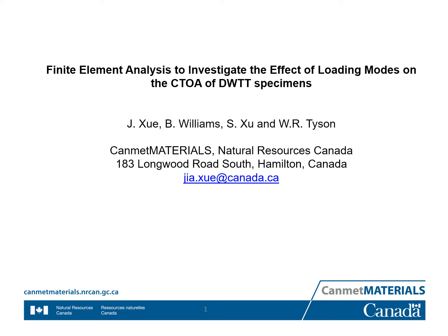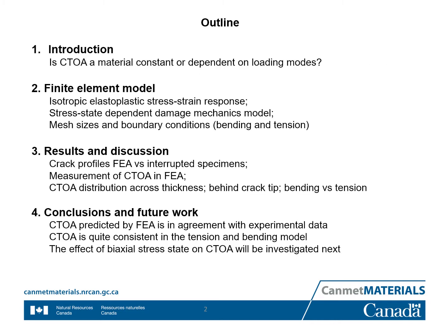The topic of my presentation today is finite element analysis to investigate the effect of loading modes on the CTOA of DWTT specimens. The outline of this presentation will have 4 sections. In section 1, we will have a brief introduction about the background of CTOA, which is short for crack tip opening angle. The major question we want to answer in this presentation is: is CTOA a material constant, or is it actually dependent on loading modes?